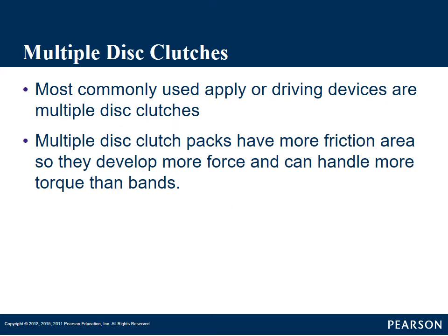When we're talking about our multi-disc clutch packs, these are the most commonly used apply or driving devices in a transmission. They can be used for holding, but most commonly used is the driving device.